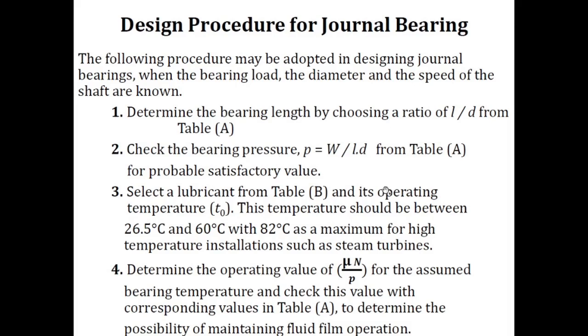Here I have listed the design procedure for the general bearing. We'll quickly see how the bearings are designed, and we'll go through one numerical so that you get the idea of how to design general bearings. This is the procedure where the first step is that you have to determine the bearing length by choosing the ratio L upon D from table A.